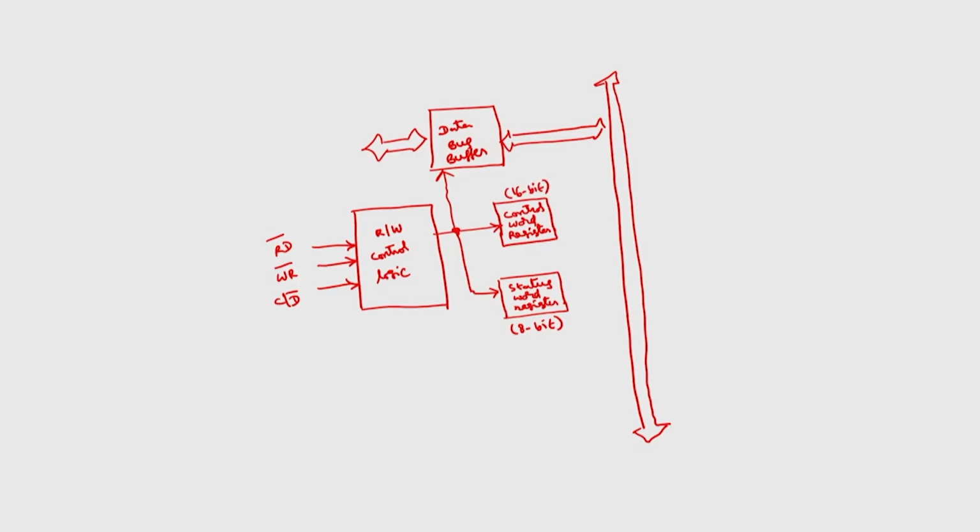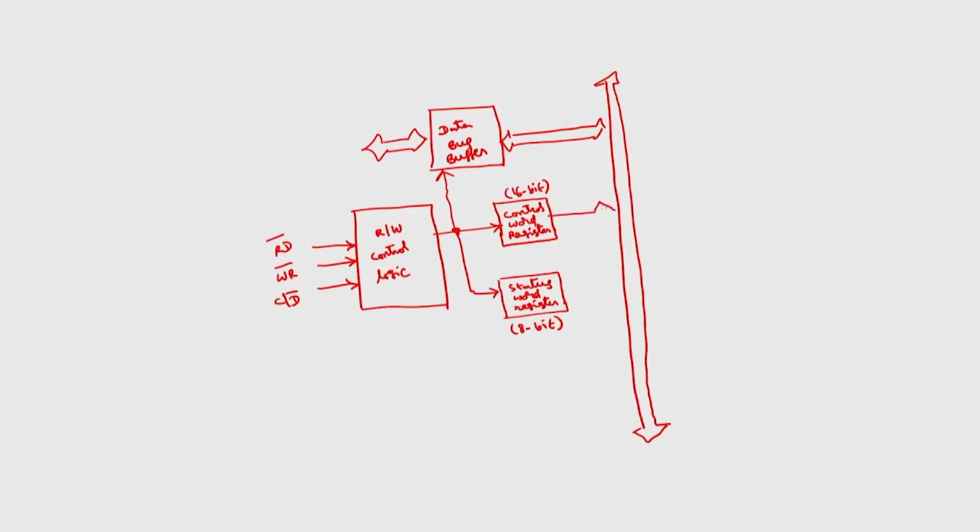So, the microprocessor will write some data into the control register. So, the direction will be from the control word register to the internal data bus, whereas the microprocessor can read the status of 8251, so that the direction will be like this. As the name implies, in case of the control word register, because it is going to be written, write bar is 0 here.